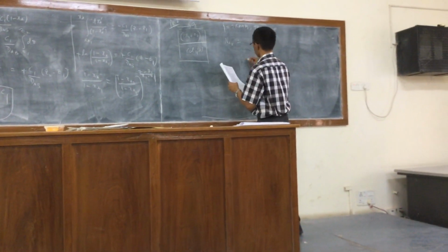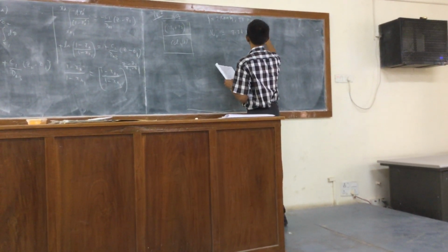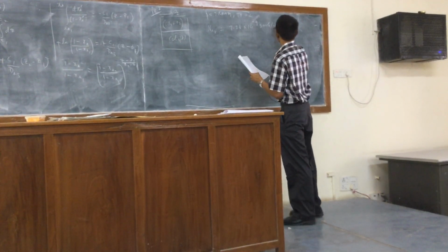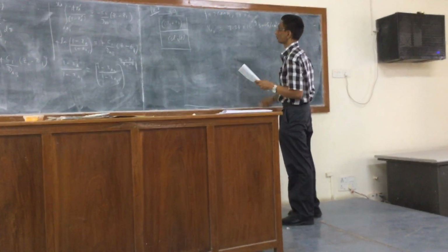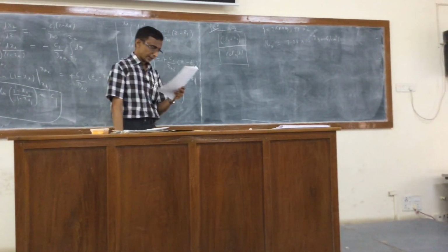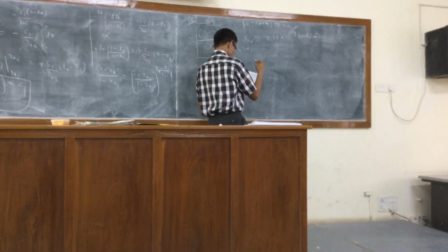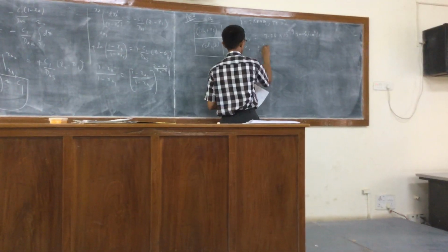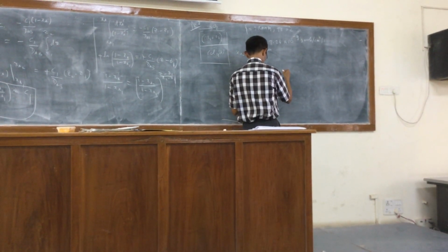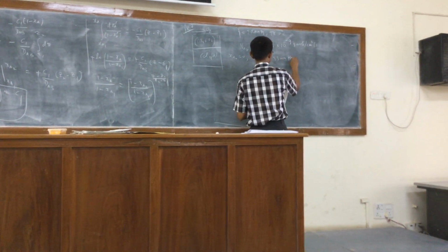That has been measured to be 7.6 times 10 to the minus 9 gram mole of CCl4 per centimeter square per second. And then XA2 is taken, which is 0. Also given, the saturation pressure of A, that is CCl4, at 0 degrees centigrade is 33 mm Hg.